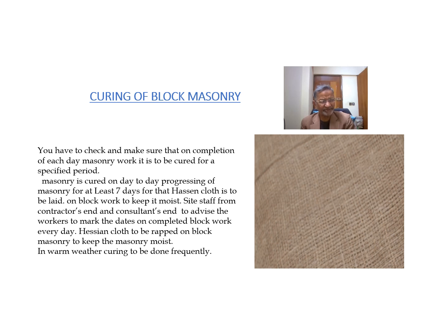Curing is mandatory for a specified period of at least 7 days in winter, and about 4 to 5 days in summer.